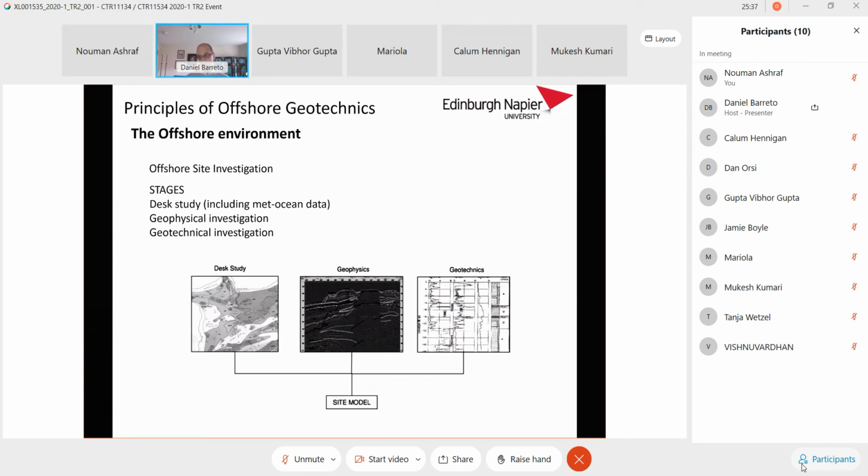And that includes, particularly if you are dealing with wind farm developments or oil and gas structures, some meteorological and oceanographic data to be able to estimate things like extreme wave heights that drive wave forces, and magnitudes of wind and their directions across the year, so you can again estimate representative or significant wind magnitudes for the design of those structures.